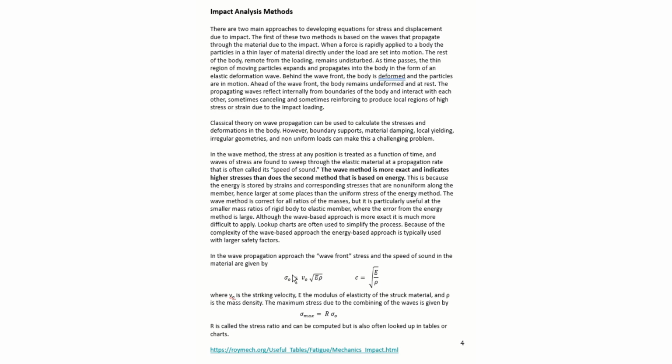Classical theory on wave propagation can be used to calculate the stresses in these cases. However, these are really tough problems because the boundary conditions are not exact. Material damping is not completely understood. Changes in geometry and non-uniform loads all make wave propagation methods pretty difficult.